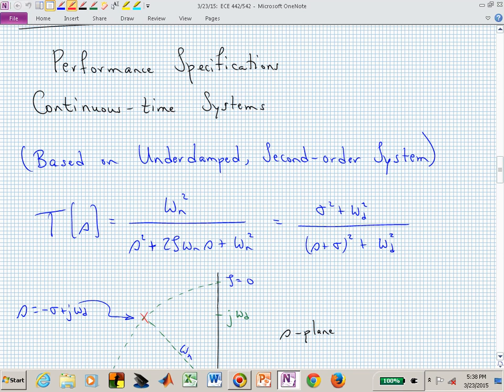The pure two-pole system. Pure meaning 100% pure, that's where the ivory soap comes from. No zeros, no finite zeros. We simply had 2 finite poles, and those are located according to this right parameterization at S equal to minus sigma plus and minus J omega sub D. That's one benefit of writing the parameterization as in the right. The one on the left or in the middle, for that parameterized transfer function, we have the natural frequency omega sub n and the damping ratio zeta, and sometimes it's nice to think in those terms.